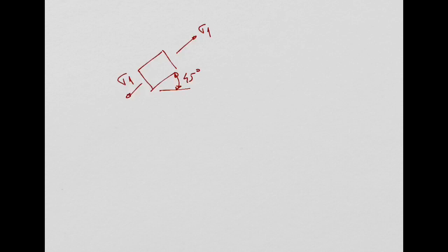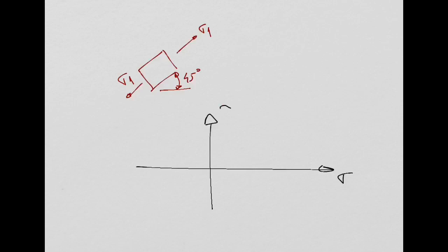What you have to do is, how do you draw this Mohr circle? Well, first you need to put the axis here, right? You need to start with one shear plane, this one, where you have sigma 1, so you put sigma 1 here. Yeah? You have only a direct stress, right? Shear stress is 0, so shear stress tau is 0 in that shear plane. You have only a direct stress in this sigma axis, which is equal to sigma 1, right?